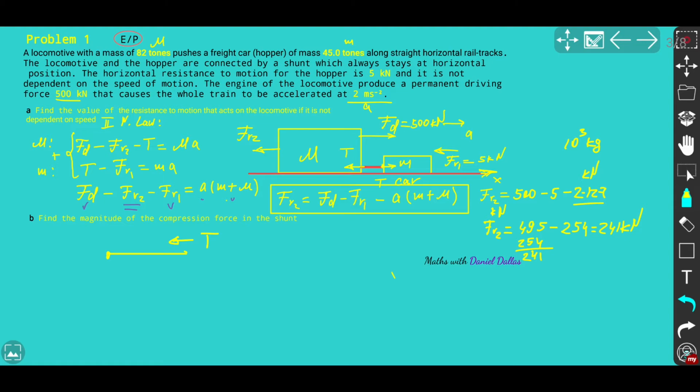And you'll be right. But because the mass of this shunt is negligibly small, if you try to complete the equation, mass of the shunt times acceleration, and you apply this approach, you'll simply get 0. Why? Because in reality, the forces will be different. For example, this force is going to be T1, this force is going to be T2. And you'll have the difference, because the shunt is going to the right: T2 minus T1. In the general case, it's not equal to 0, but you assume that the mass of the shunt is 0. So hence you can think that T1 is equal to T2.